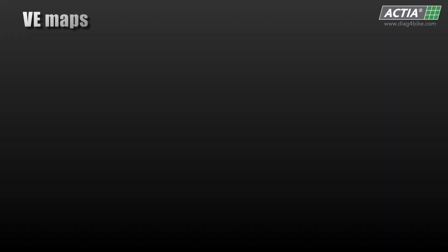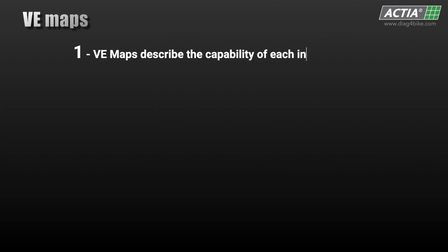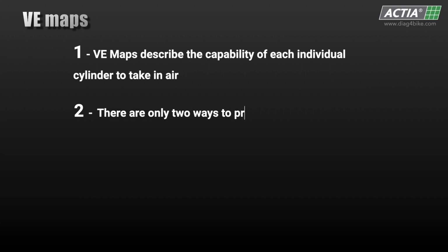The most important thing we need to know about VE maps is therefore: first, VE maps describe the capability of each individual cylinder to take in air. Second, there are only two ways to properly tune VE maps, and these are by no means manual changes that reflect the wishes of the owner of the motorcycle or of the tuning operator.